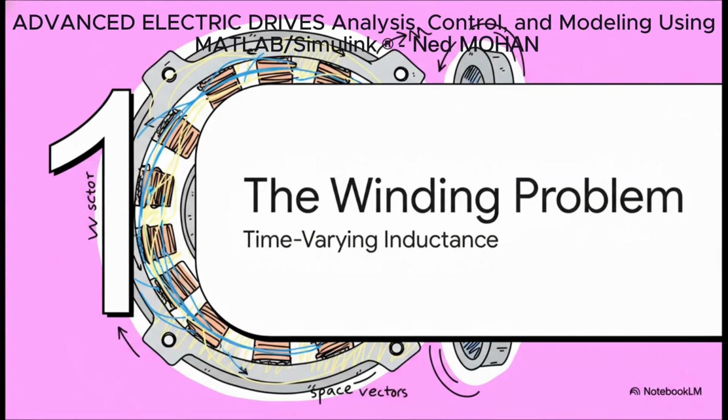Okay, Section 1, the winding problem. So what is the real challenge with time-varying mutual inductance? Well, let's get right into it. The single biggest hurdle when you're trying to model an AC machine, especially dynamically, is the magnetic coupling between the stator and the rotor. See, this coupling isn't some nice, neat constant. Nope, it's changing every single instant that the rotor is spinning.